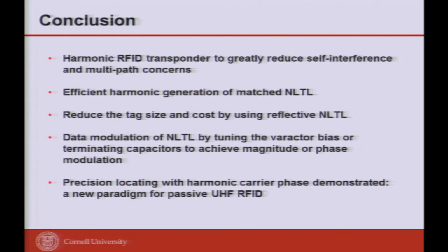And I showed you the nonlinear transmission line. It has a special property of no spectrum spilling. By setting the Bragg frequency, you get self-impedance match, and a reduction of phase noise, which I don't understand why, up to today, but by measurement it's reduced.